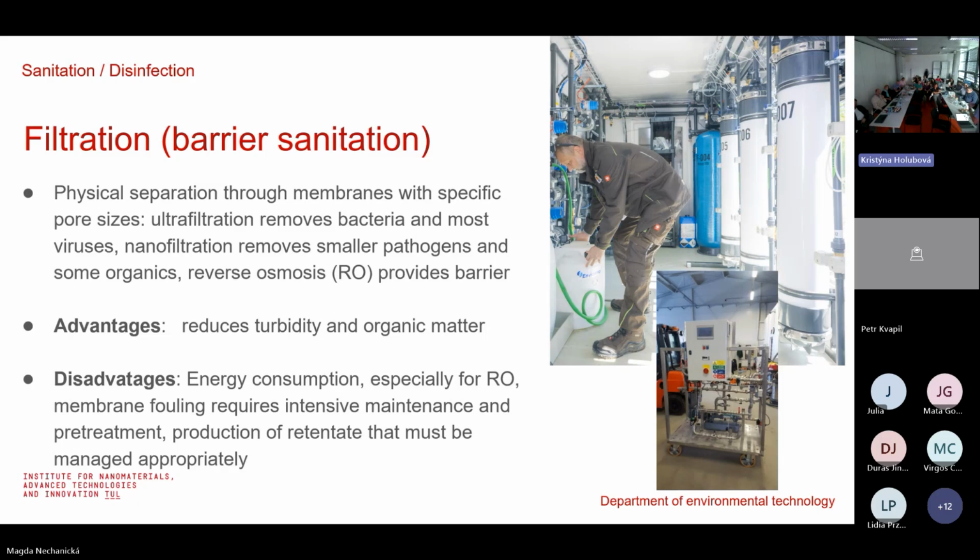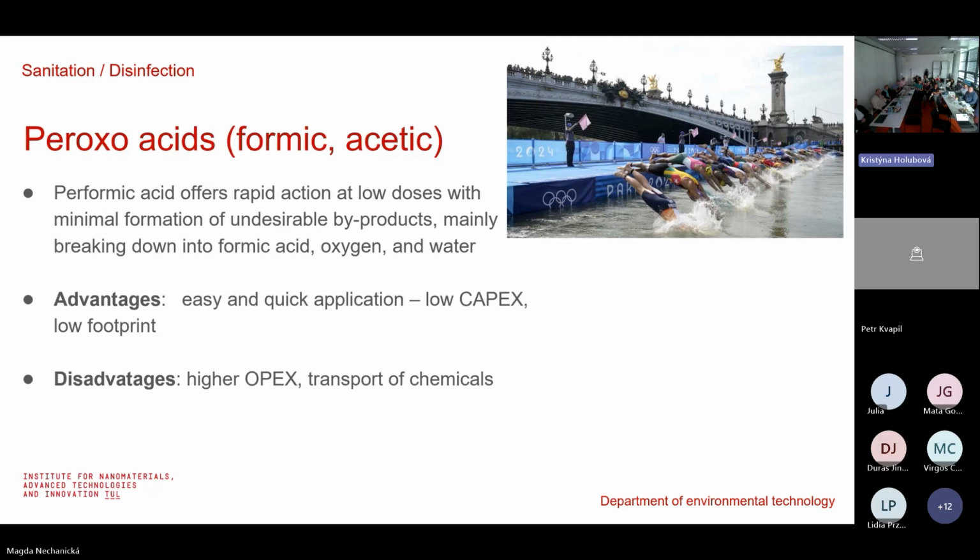Filtration barrier. Here you can see the director of the Liberec pilot. As I mentioned before, we applied very dense ultrafiltration membranes. The pore size is less than 10 nanometers, so we are able to remove almost all microorganisms. Peracetic acid, as I mentioned before.